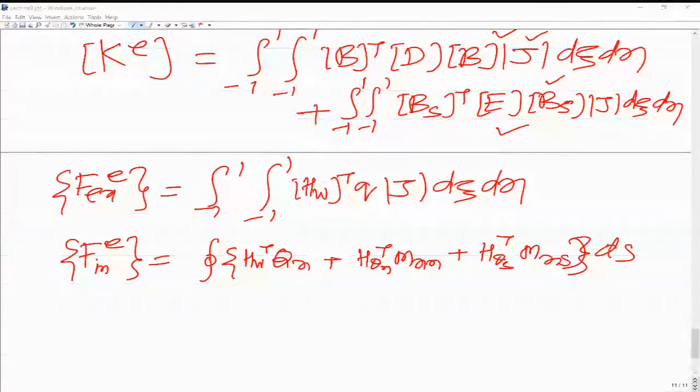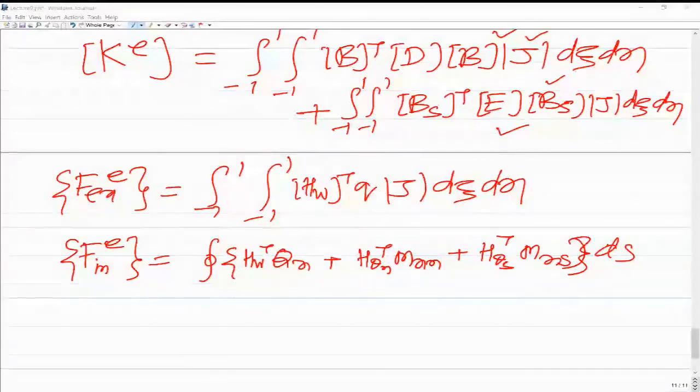So now you are talking about the classical plate bending element, right? Yes, sir, in the classical plate bending element, because the derivatives are also involved. There, the primary variables are w, del w by del x, and del w by del y. So if we have a problem where the primary variables are the basic variable and its derivatives, then you will get the compatible element, and that too actually a rectangular element, through the additional degree of freedom. But if the primary variables are only without derivatives, like here we have w, theta x and theta y, then you can get the compatible element just by formulating the element in the natural coordinate space.